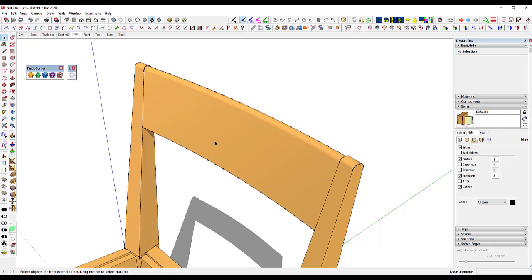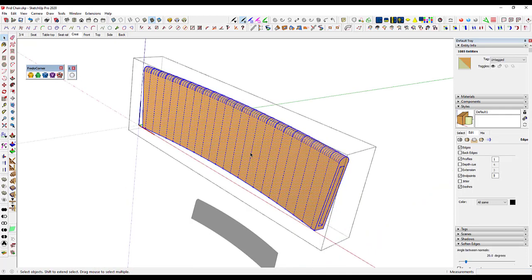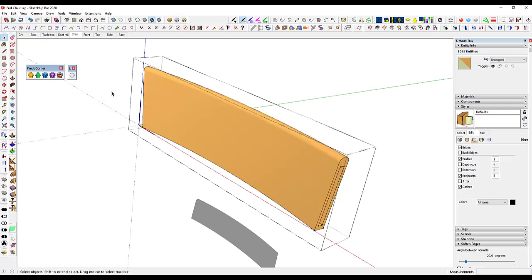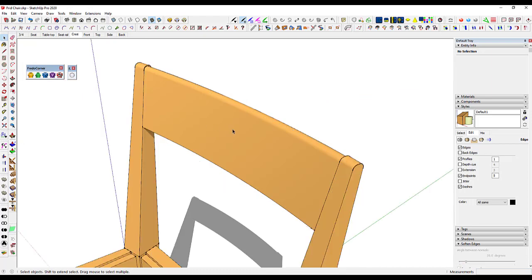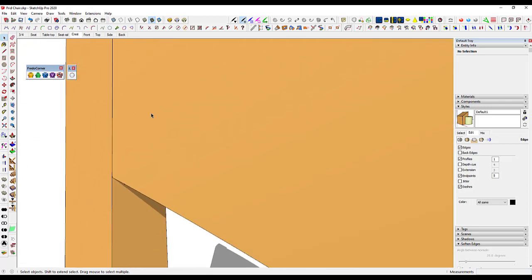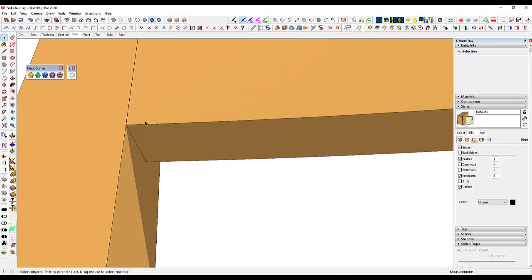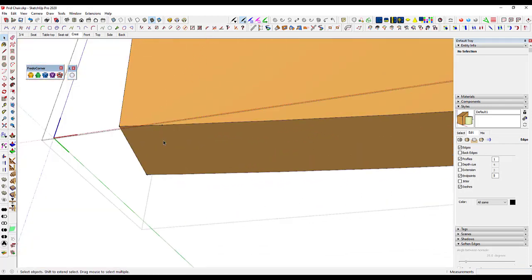edges. So to run this, I triple clicked on the geometry there on the component and opened the component for editing and selected all of that geometry. And then I'm just going to click on weld and let it run. And when it finishes, it's cleaned all of that up except for one right in there.